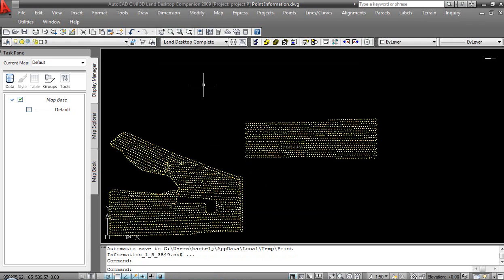So with that being said, leveraging Civil 3D as a tool to supplement Land, what that does for us is, first, it allows us to work with points without the points being dependent on a database. Second, the visualization of those points is pretty much effortless. We can adjust their size very quickly just by setting the scale at the bottom of the screen. We can also adjust their display with respect to labels by applying one of the default styles.